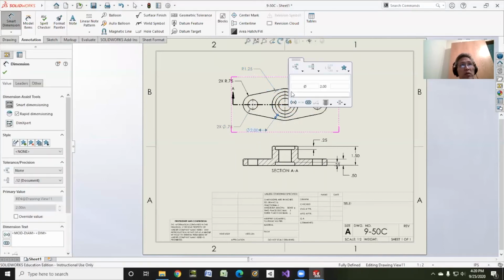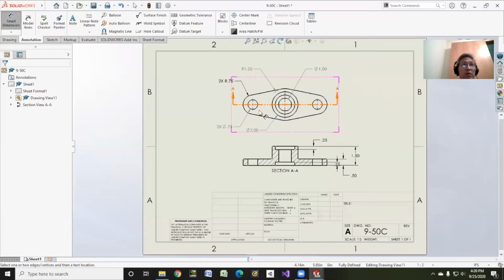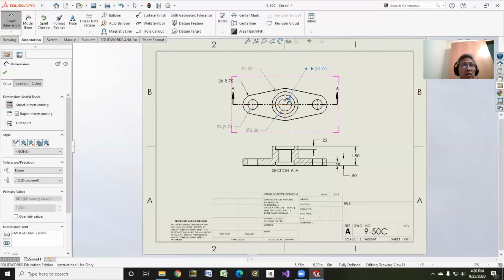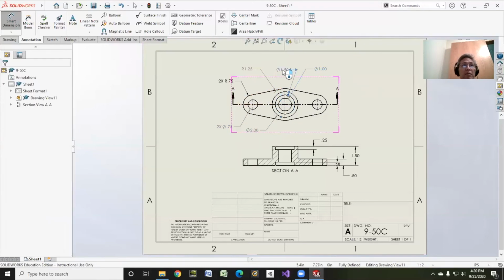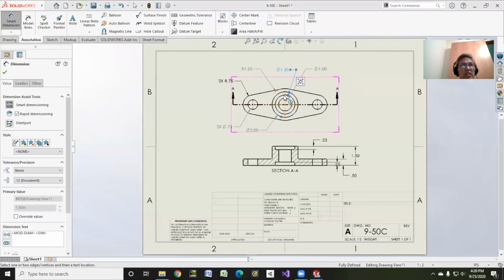All right. Now you're probably wondering why. Well, what about this guy here? How come you don't dimension that? Well, this is a cool dimensioning practice where I can do one dimension for this radius, or this diameter that I did not put in there. I'll just leave it there for a minute. We're going to get rid of it. And both this and this depth there for our counterbore.